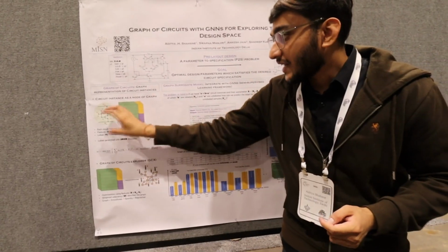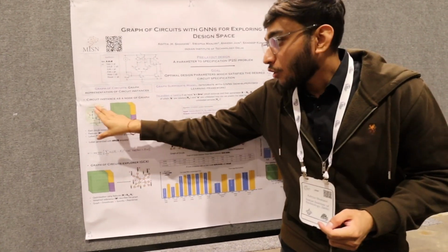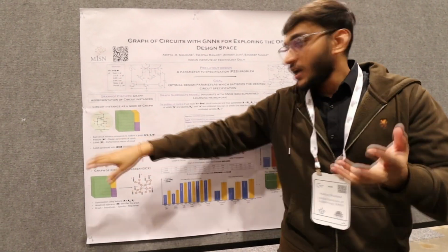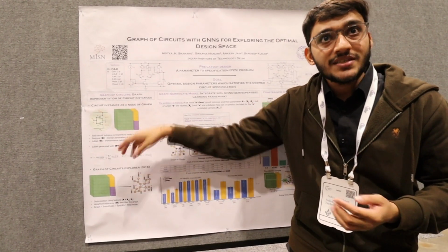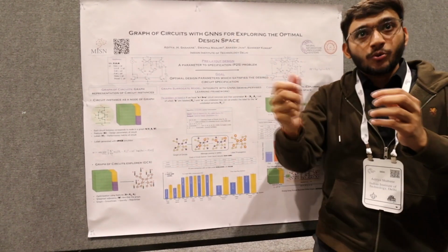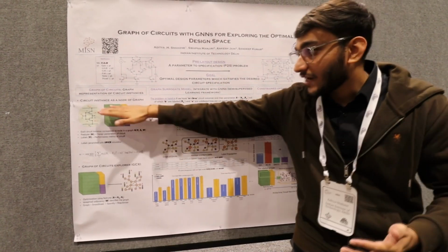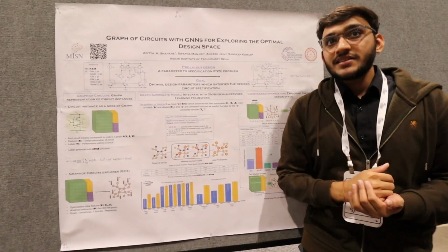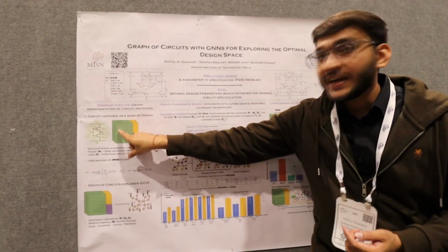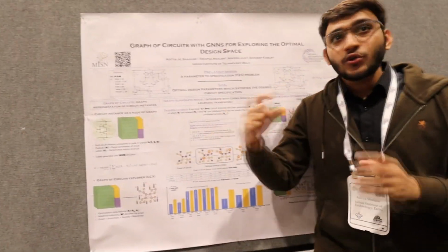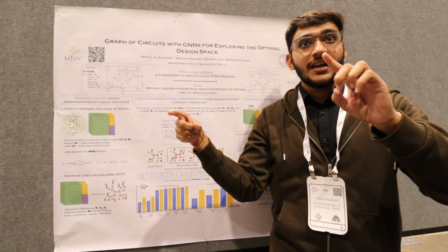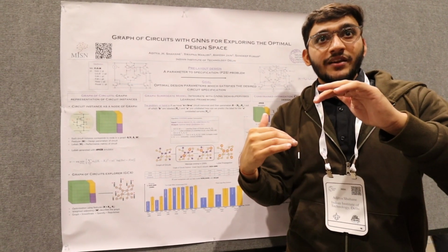As I mentioned, let's say this is a circuit which you have in hand. The VDD can go to 1, 1.2, 1.5, 2.5. All these real values are going to be VDD. So these will contribute to different instances. Similarly for W1, it will be maybe 100 micrometers or 200 micrometers, something like that. So that will be another row. So it is a stack of all of them. The i and the j are going to be different instantiations of the circuits. So this is Xi and Xj. So in that way it is going to be O(N squared), because each one will be compared with all the different features available within that particular stack.